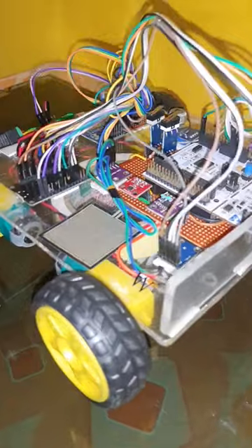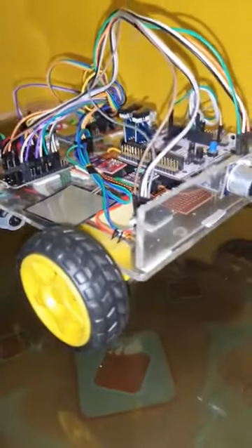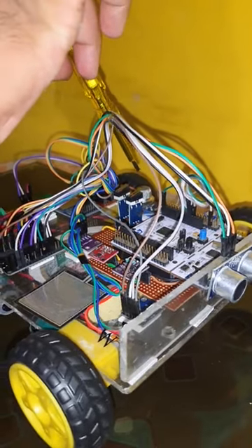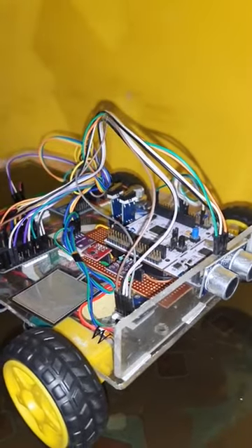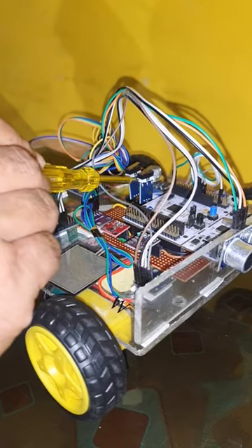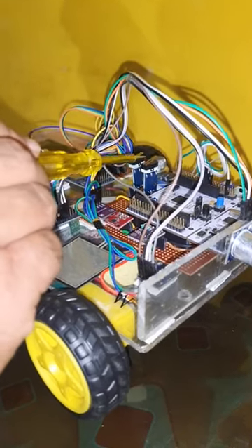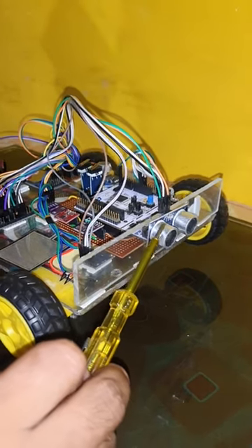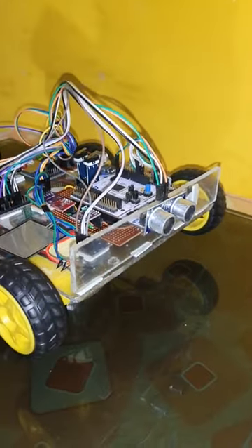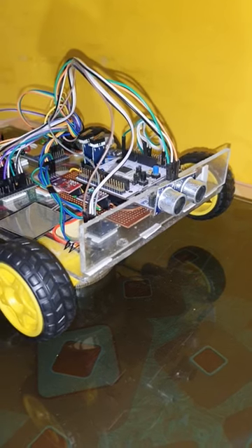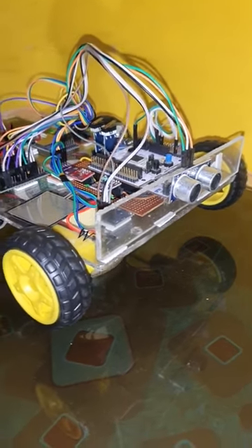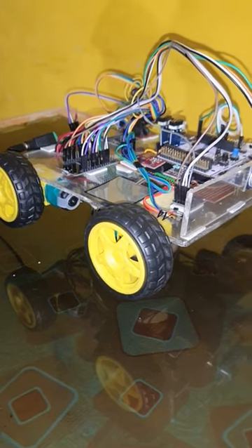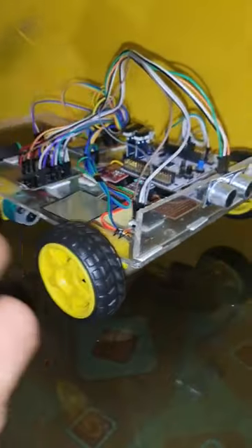The conditions on the sensors are as follows. For the MQ2 sensor, if the driver is drunk or alcohol is detected, then the car won't start. Another condition is for door status: if the door is open, the car won't start. The third one is the ultrasonic sensor. If the distance between the two cars is between 20 cm and 30 cm, then the car reduces its speed automatically. And if the distance is below 20 cm, then the car applies an immediate brake.